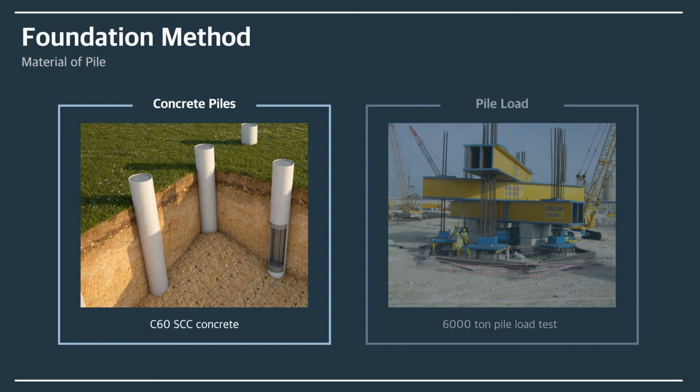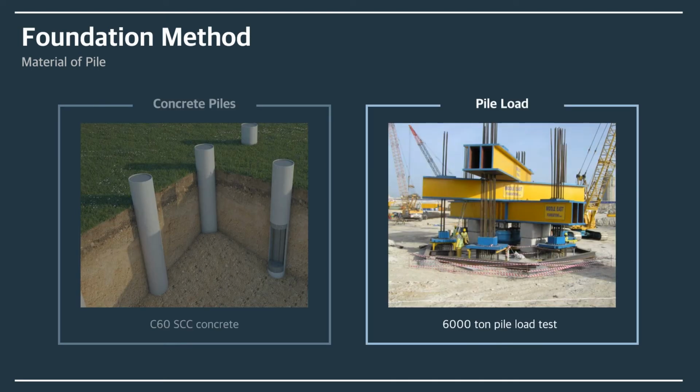The concrete mix for the piles was also enhanced, designed as a fully self-consolidating concrete to limit the possibility of defects during construction. The diameter and length of the piles represent the largest and longest piles conventionally available in the region. The 6,000 tons pile load test also represented the largest magnitude pile load test performed to date within the region.